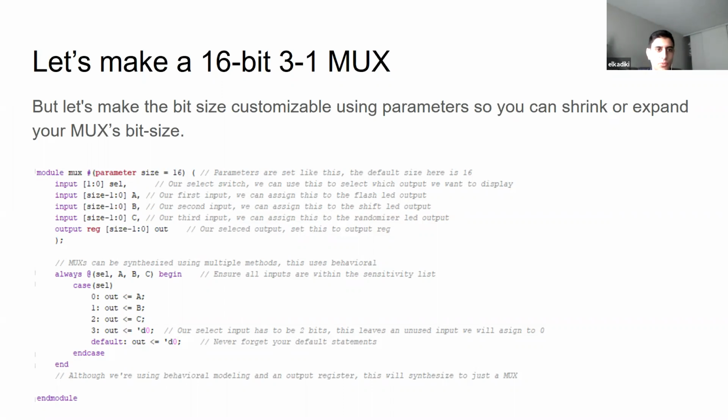But it always helps to understand the warnings in Vivado. If you can look at the warnings and try to piece together what it's complaining about, it can help debug a lot faster than writing a test bench. If you go through the logs, generally it'll tell you what line or signal at least is causing the problem. If you start early on trying to figure out what the messages mean, you'll have a better time later on.